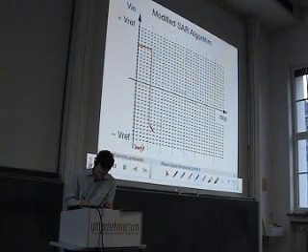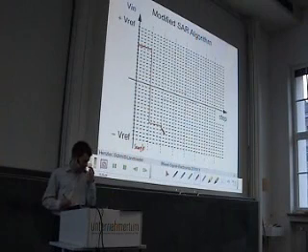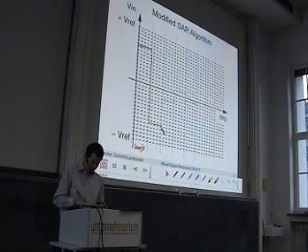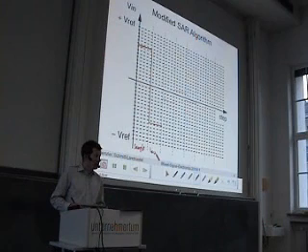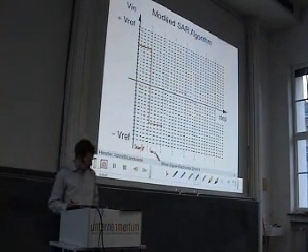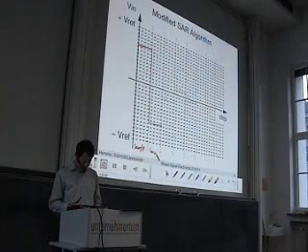And then we end up with this value. Okay. Then we have to check, is this larger or smaller than 0? And of course we can see it is less than 0. So we add Vref over 4 to this result. No, we add Vref over 2.